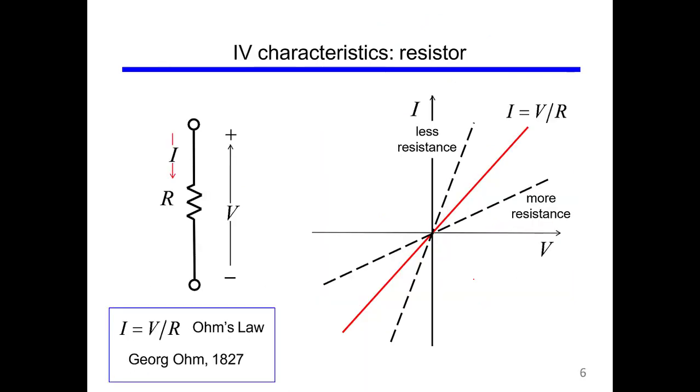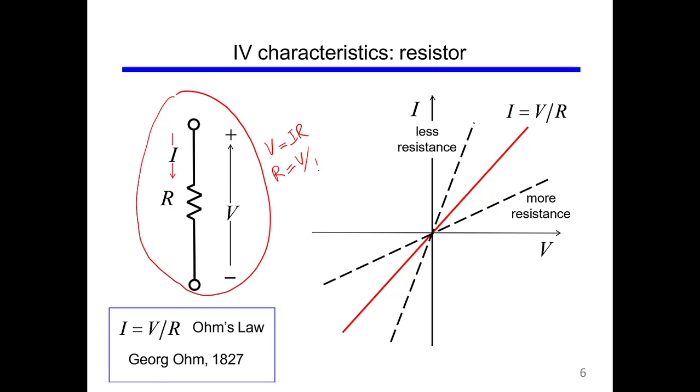Now, in order to understand the characteristic curve of a transistor, let me take you back to Ohm's law. On the right you see a resistor. This is well known to electrical engineers, and if you apply a voltage V across a resistor, you all know that V is equal to IR, or R is equal to V by I. So if you plot V on the x-axis and I on the y-axis, you can plot a curve, and the slope of this curve is related to your resistor.